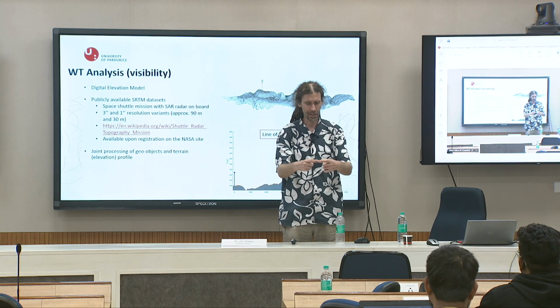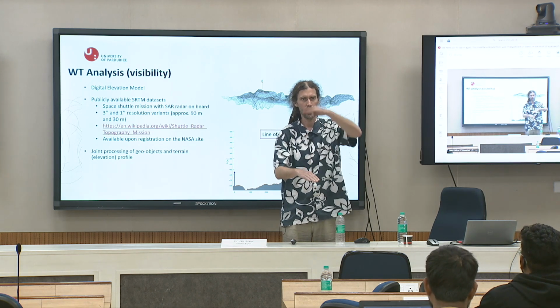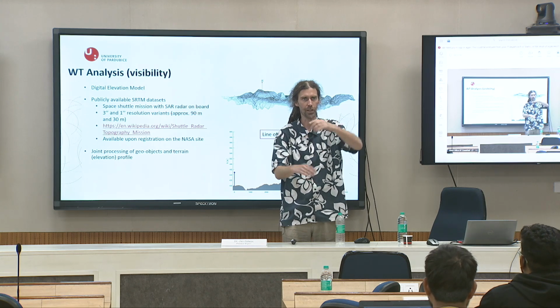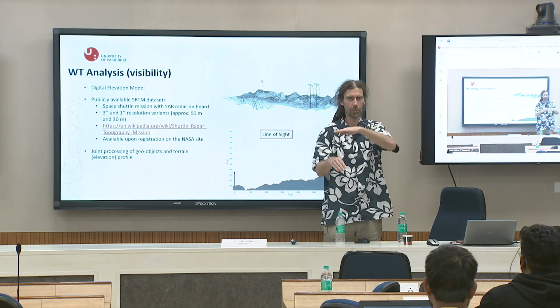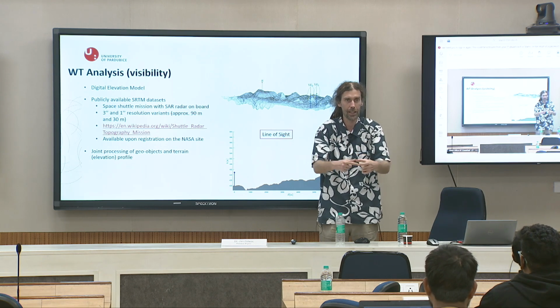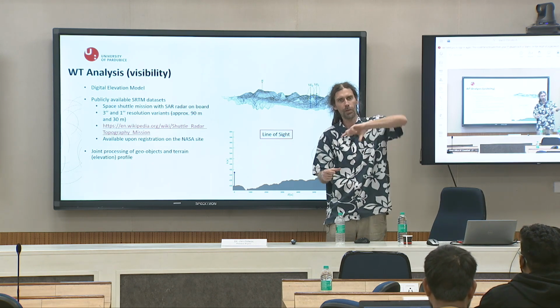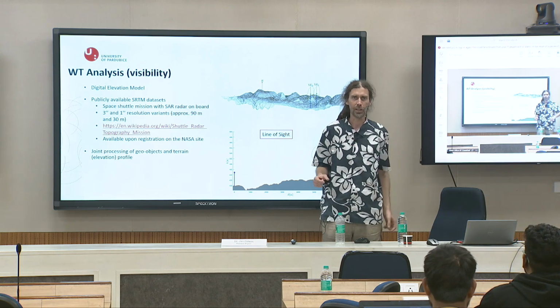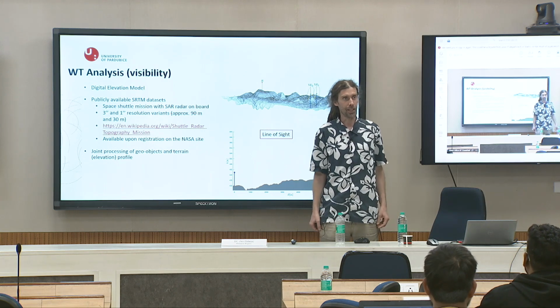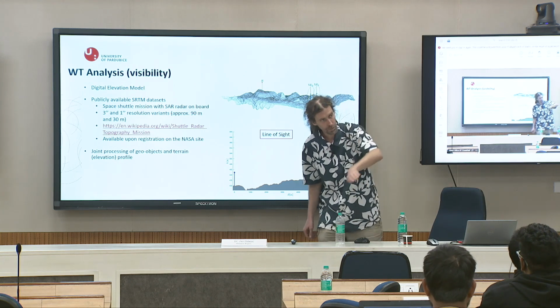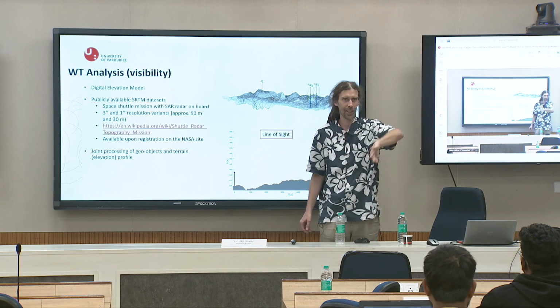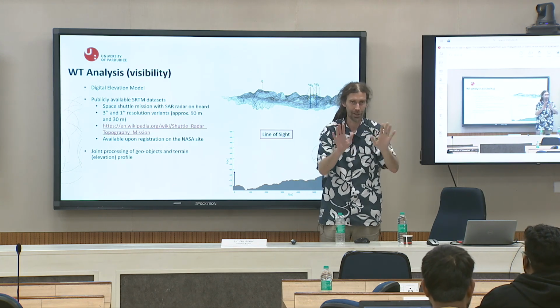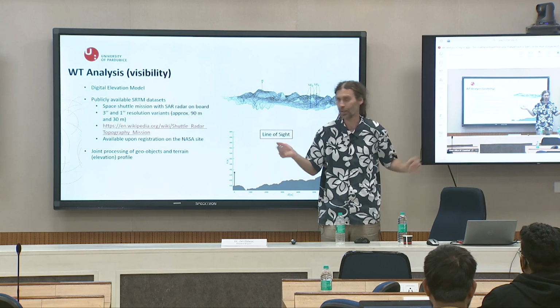Because imagine it is like a tile of 30 meters by 30 meters with some elevation, and the next tile will have a different elevation, but still constant over 30 meters by 30 meters. So in case there are some 5-meter valleys in these tiles, you can't see them because you don't have enough resolution.